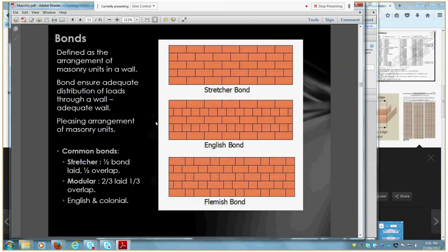With our double brick, yes, it's got fantastic thermal mass, but you've got to get some insulation onto that somehow. You might do that with, say, a compressed straw panel on the inside that will give you your R value, or you might use expanded polystyrene foam panels on the outside with the mesh, and then render that. So you can use your double brickwork as thermal mass inside your house and still provide insulation on the outside. But you've got to get your insulation onto there somehow.